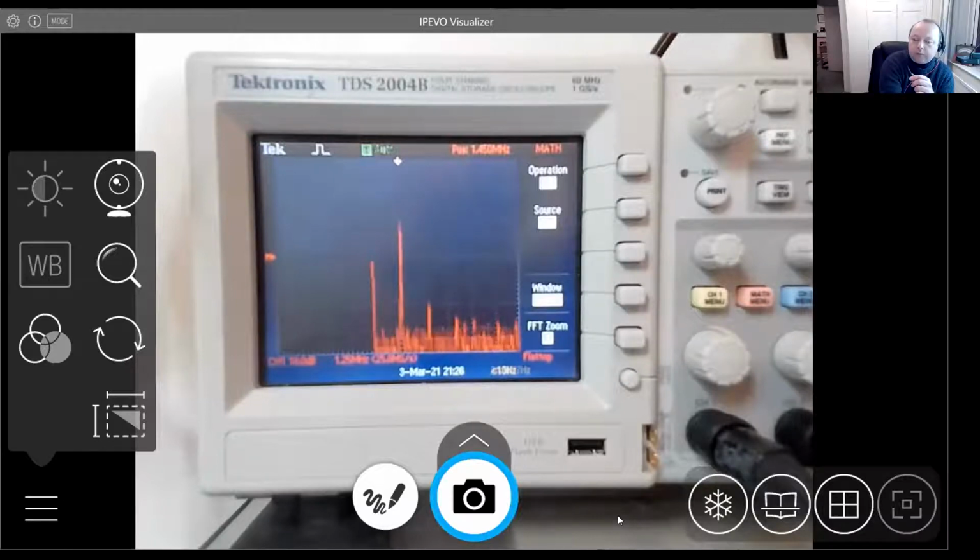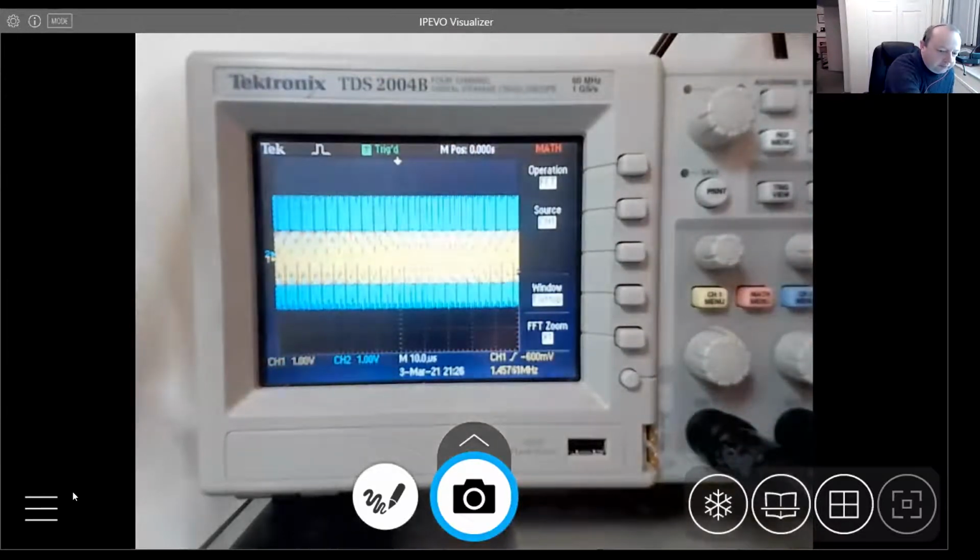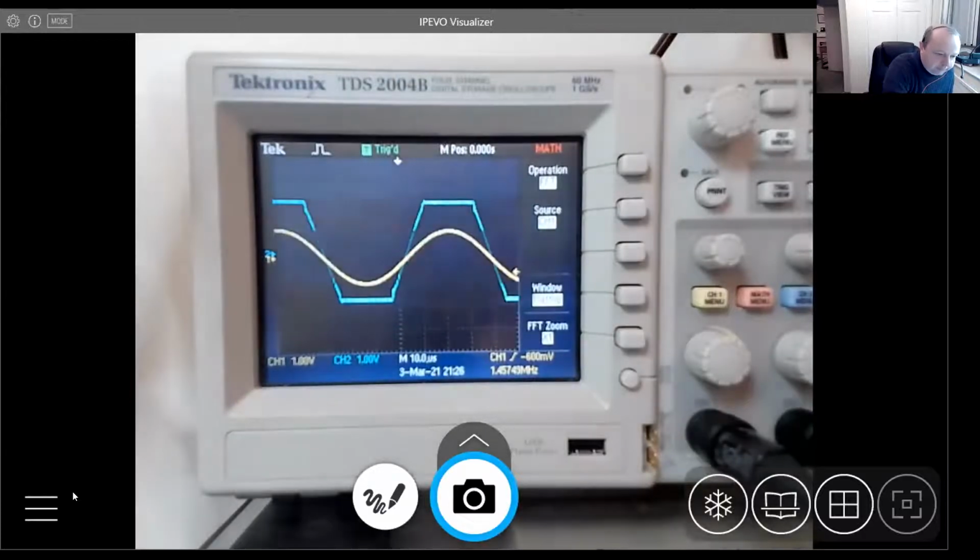So if you start getting clipping in your amplifier, not only are you distorting your waveform, you're also starting to introduce unwanted frequencies. So if you're doing some frequency analysis and you've got clipping, you'd certainly start to upset your amplifier. And if you're doing some maths, for example, you start to upset it. So something to be aware of. It's not always as straightforward. Right, let's drop that back there. There we go, so there's our clipping.